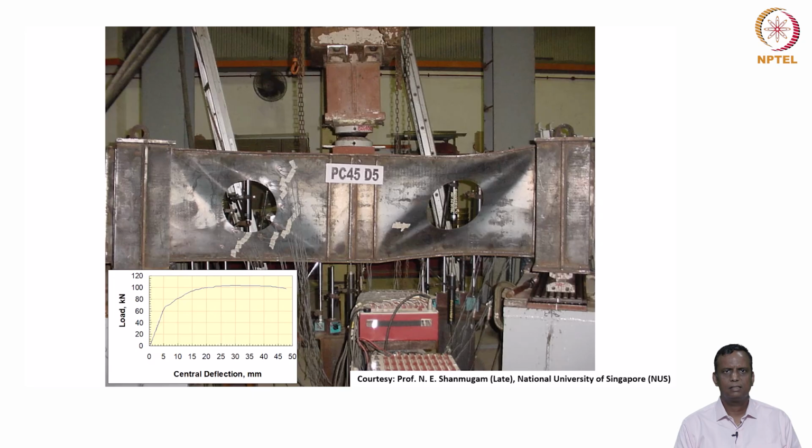So you can see that the tension field action has visibly been displayed experimentally by this short video. You can see that at 60 to 70 kilonewton is where the first formation happens. As a result of the first formation of the tension field band, there is an increase in capacity, which means that stage 1 is basically below 60 or 70 kilonewton, where the elastic critical buckling stress is taking care of the load. After the formation of tension bands due to shear buckling, post buckling kicks in, and after 60 or 65 kilonewton, there is an increase in load.